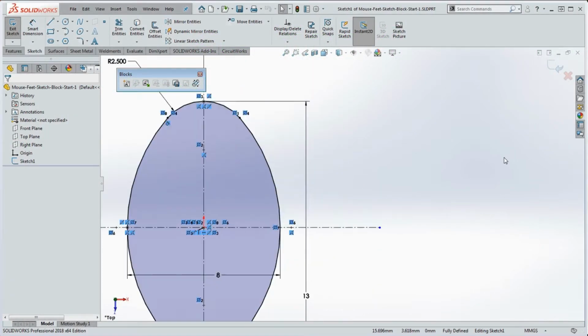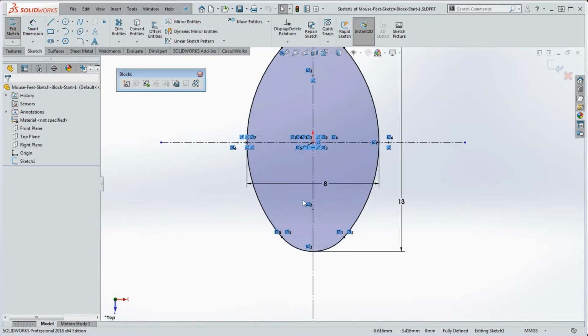Okay, so we're almost ready to create that block. So in order to get that wall in here, we want to have enclosed geometry that's kind of on the edge. So we're going to have to define the inside and the outside of the wall, where the inside is going to be kind of like a donut hole in a way.